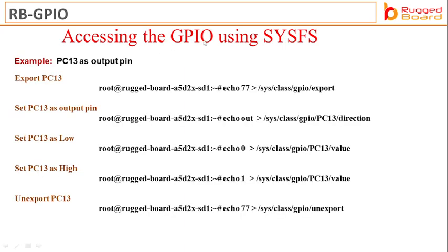Now, accessing the GPIO using sysfs. Sysfs is a pseudo file system for all the devices and drivers. It creates device files in the sysfs class directory, and all the drivers are represented in this directory.